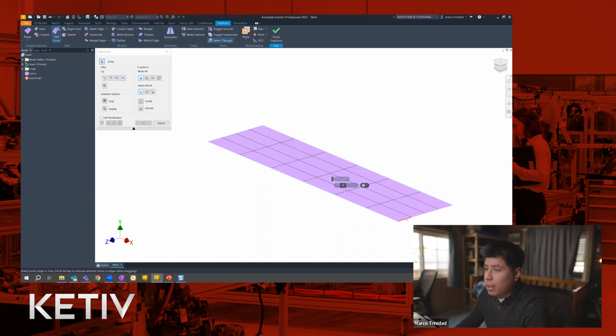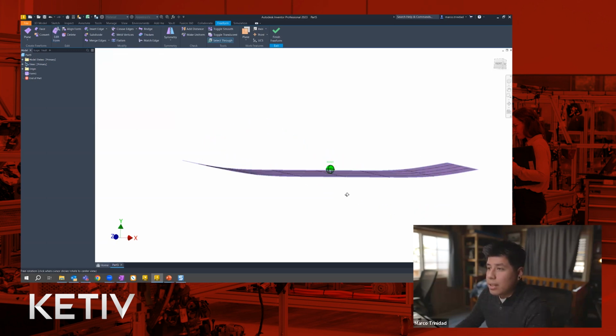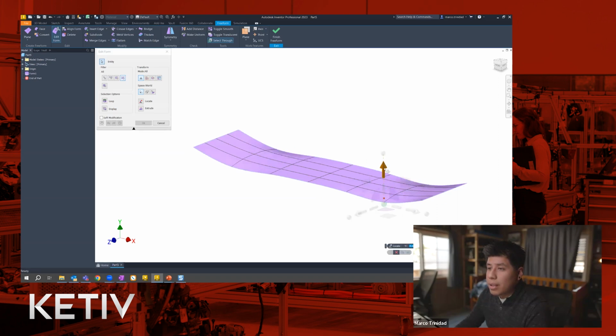And I'm going to go ahead, and the first thing I want is to actually grab each of these edges and create the top end of each edge for the surfboard or for the skateboard. So I'm going to just go ahead and go up right there and click check. And then you can see that this is symmetrical. Because I added that symmetry, I only had to grab it from one side. So now I'm going to go ahead and edit form one more time. And I'm going to grab this point here and bring down the edges a little bit. And then once again, click OK.